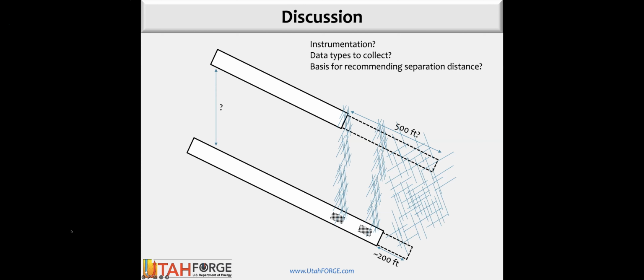Luke, that flow rate right now, at least for the submersible pump on the outflow side, the production pump, 250 GPM is something we have planned. Maybe we can go a little higher. That really comes to between 12 and say 15 or 16 kilograms per second, depending on what the density of that fluid is. 5.9 inches is pretty tight, but we're trying to have a pump that could be on a variable frequency drive, so we could essentially meter those flow rates.